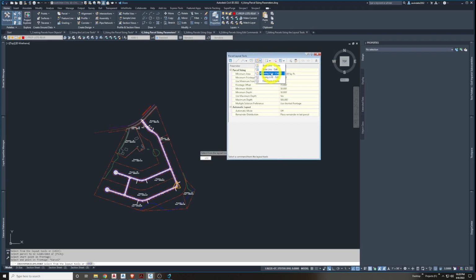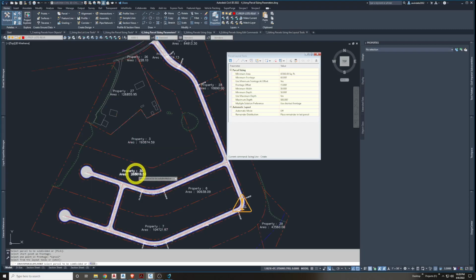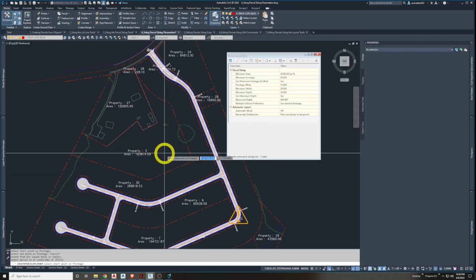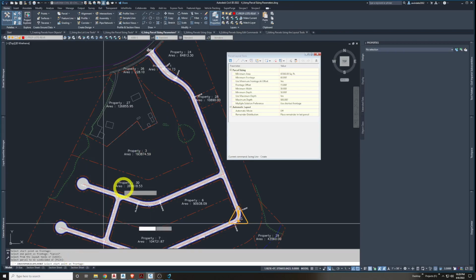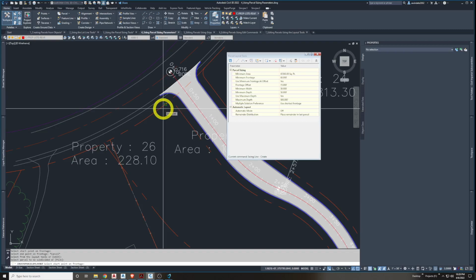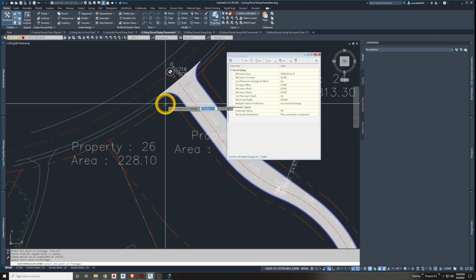So I'm going to once again do the swing line create, getting ahead of myself. And we have to pick a parcel to be subdivided. Always watch your command bar, especially on these commands. It tells you what you need to do next if you get a little confused. Let's pick the parcel. This is picking it right here. We want parcel 30. And it says we want a start point of the frontage. It says so with our heads up prompt here, and it also says it in our command bar. So heads up prompt and command bar work hand in hand. Let's pick a point. Let's go very exact to that image there on page 245 and pick there.